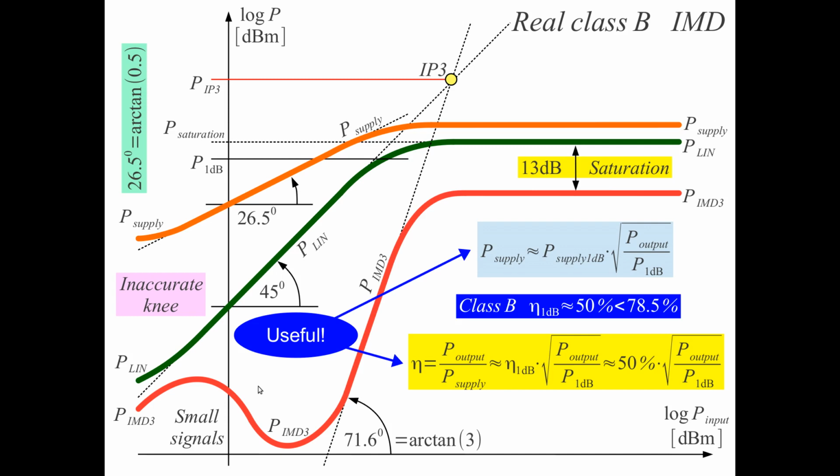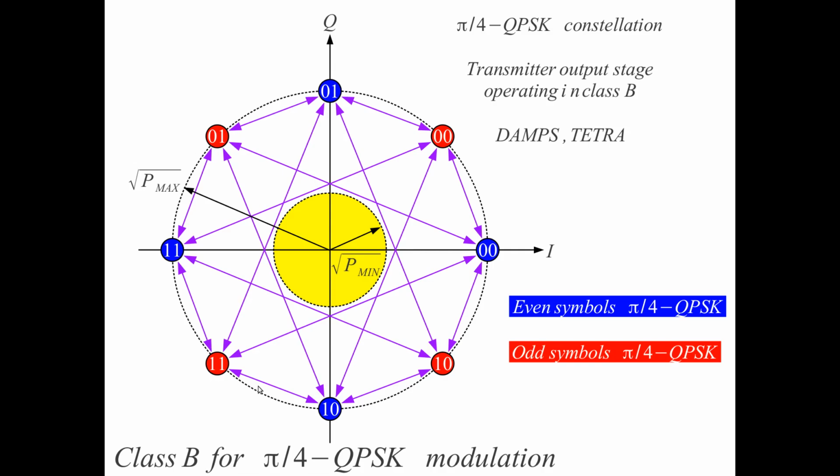But if we go to choosing suitable modulations, we can do something with modulations. QPSK modulation is a very efficient modulation for many communications, also satellite communications. But unfiltered QPSK requires a very broad spectrum. So we don't want that. We are going to filter the QPSK symbols.